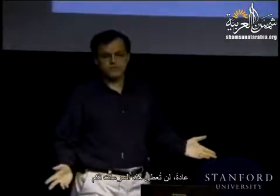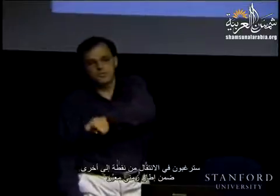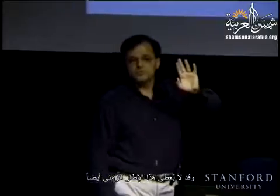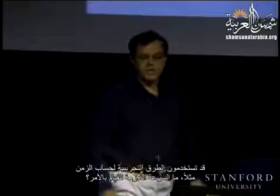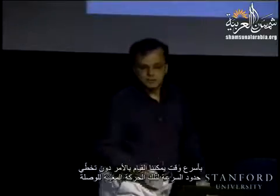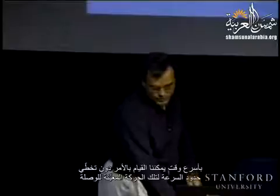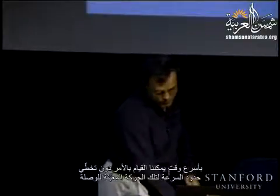Typically, you will not be given the velocities. You'll just want to go from one point to that point to that point in some time frame. And the time might not even be given as well. You just might want to set the time by heuristic, like how fast we want to do it, as fast as we can do it without going over the speed limit for that particular motion for the link.